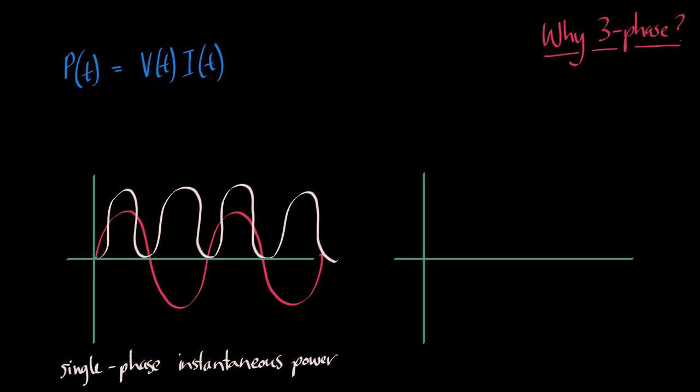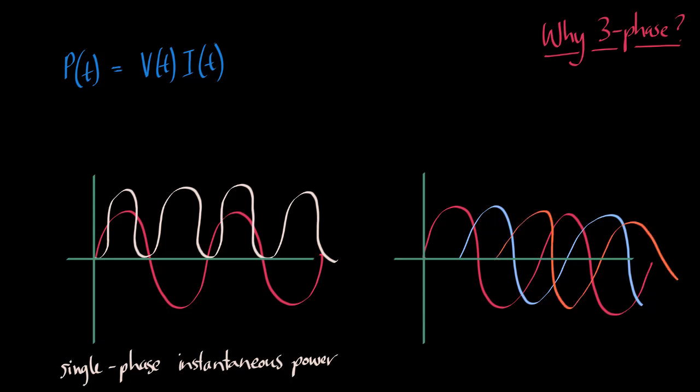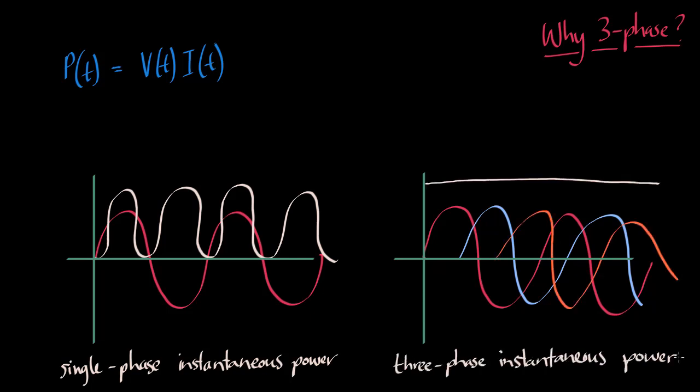Three-phase circuits, by contrast, produce a constant instantaneous power output, which is preferable. Also, when compared to single-phase circuits, the peak currents are lower for the same power flow in three-phase, requiring less material and making three-phase more economical from an infrastructure perspective. Interestingly, while higher-order phase systems can also provide constant instantaneous power, there is no benefit to having more than 3 lines for power transmission. This leads us directly onto our next topic, three-phase sources.